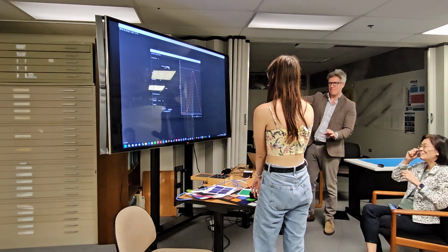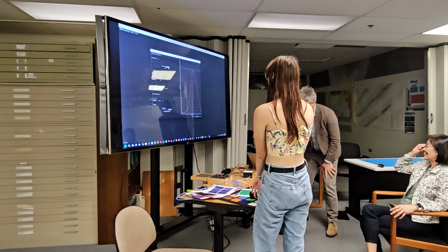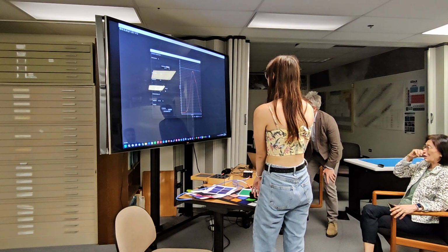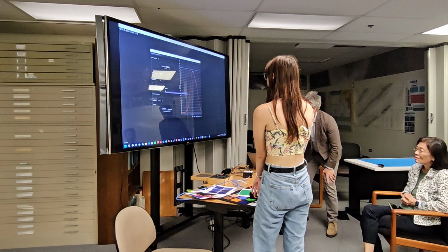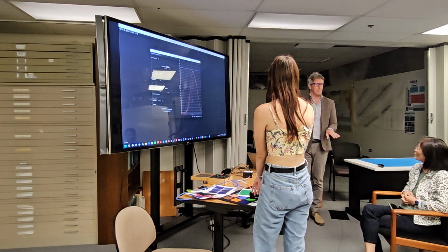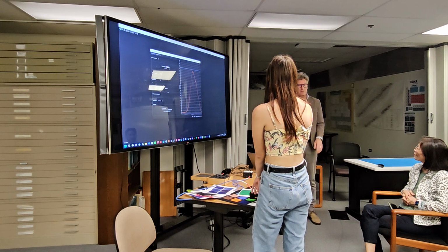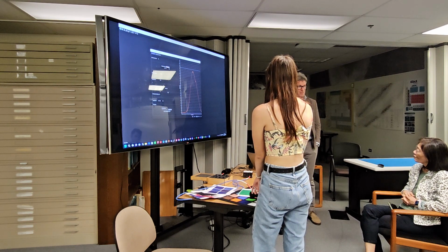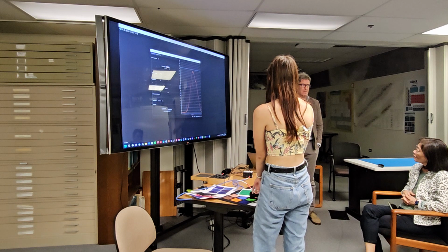So I'm not going to do any averaging or anything like that. Right, here's the first thing. First thing I have to do is collect the dark spectrum. A dark spectrum is how much light the instrument tells me it's measuring, even if it's measuring no light. And this is basically just the noise in the system, right?